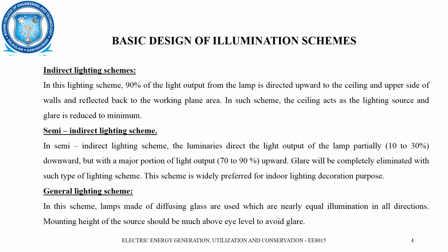General lighting: lamps made of diffusing glass are used here. The illumination level is equal in all directions, and the mounting height of the source must be much above the eye level in order to avoid glare.